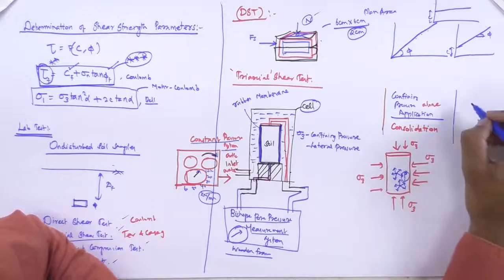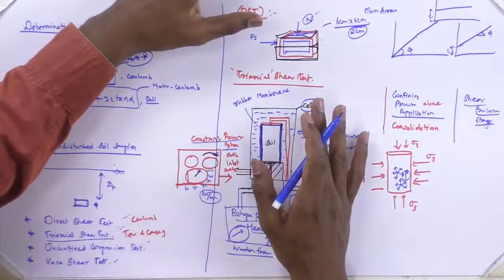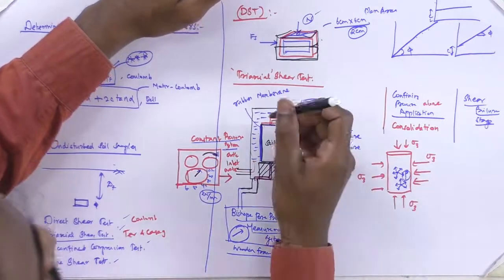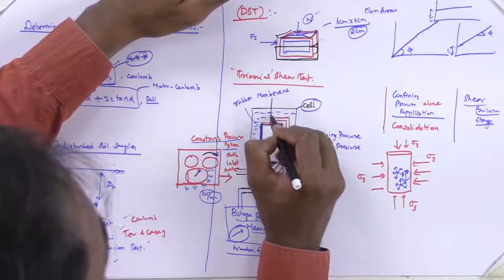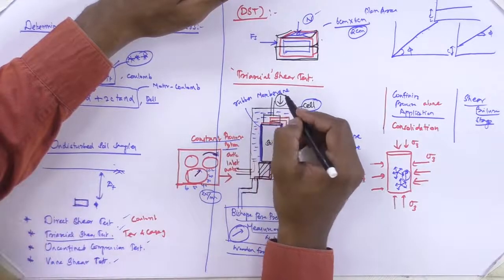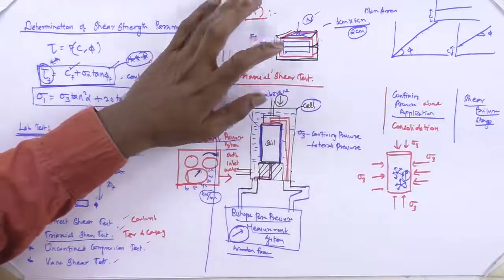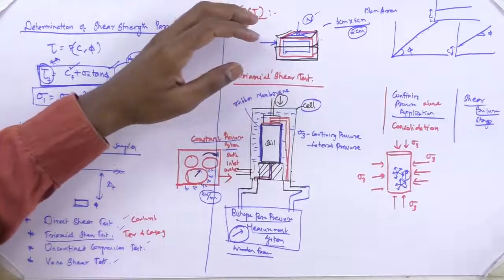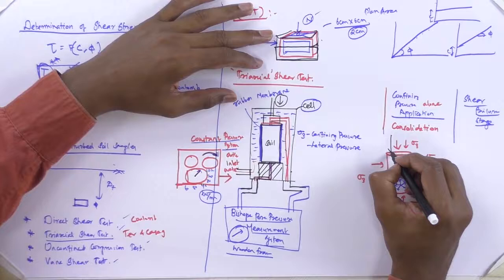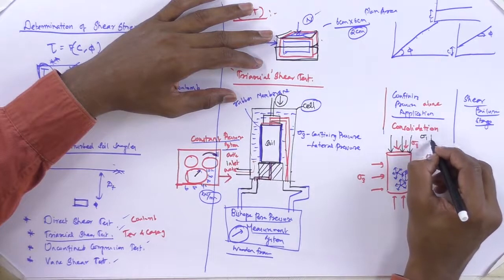We have another stage, the shear failure stage. During this isotropic consolidation process, shear failure may not occur. Once you are applying load through a proving ring or load cell, what is going to happen? The confining pressure is always already there, and you are slowly increasing sigma 1.